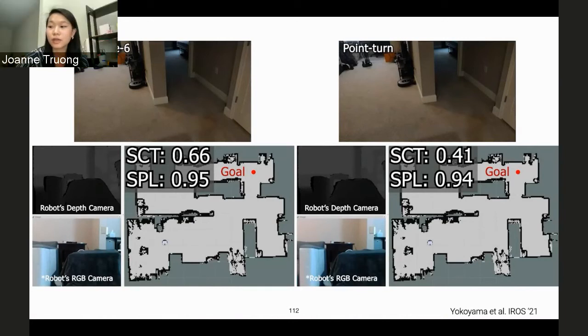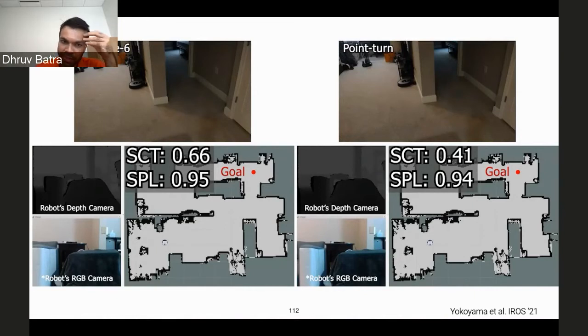Yeah, you could also add another reward term in that case. You can have an additional sensor on the robot that tells you how close it is to obstacles nearby. If it's too close to an obstacle, then you can add a penalty to the robot, and that would encourage the robot to stay a safe distance away from obstacles. Exactly. So the answer is that your reward functions are fairly expressive. If, as a system designer, you have certain preferences, you can put them into the reward function.